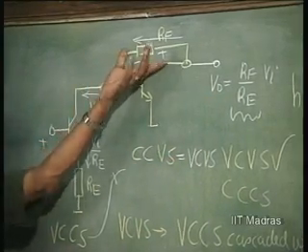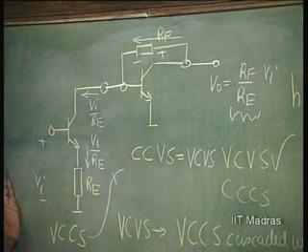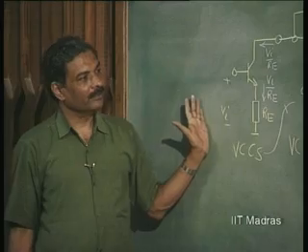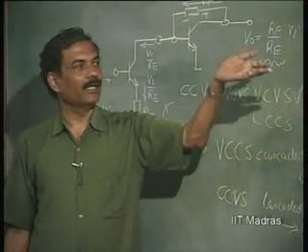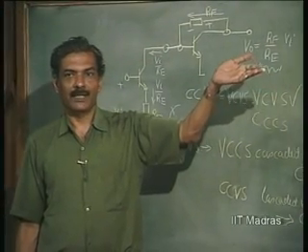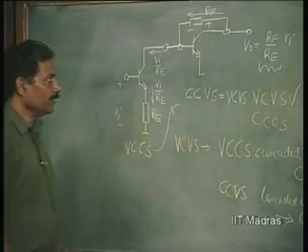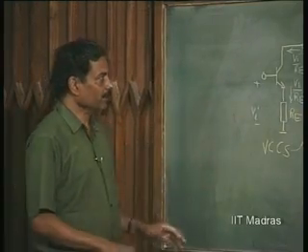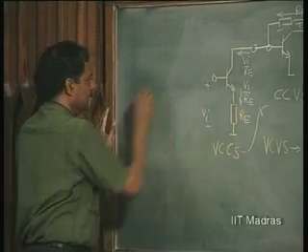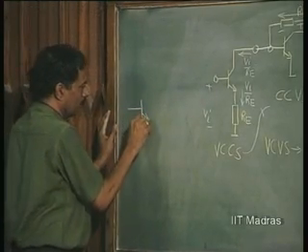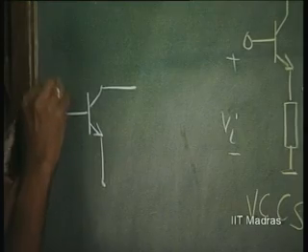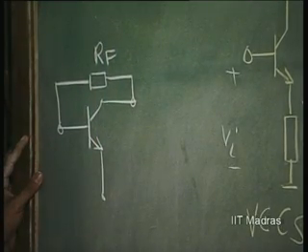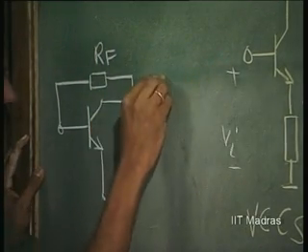So, suppose R F is 10 k and R E is 1 k, you are now designing a nice voltage controlled voltage source of gain equal to 10 without taking recourse to the H feedback with the pair that we had earlier discussed. Similarly, you say okay, I want a current controlled current source, not this, then what you do is simply put this first, R F. So, put the current controlled voltage source first and then you put this later.